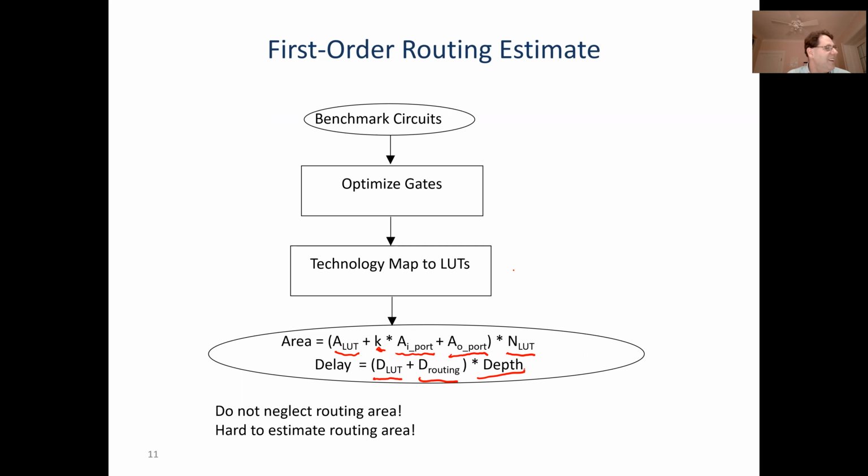Camille said I would add a factor to represent unusable area. What do you mean by that, actually? I was more thinking about, for instance, if we go from 4 LUT to 6 LUT, we're not going to be able to use all of those 6 LUTs. So just a factor that represents how much, by making these islands, is now unuseful. The more we bundle them together, the more unusable area we have.